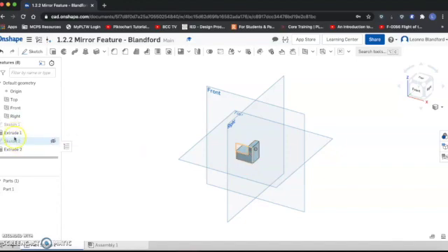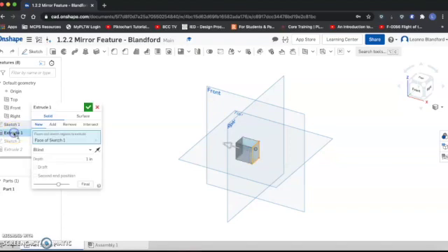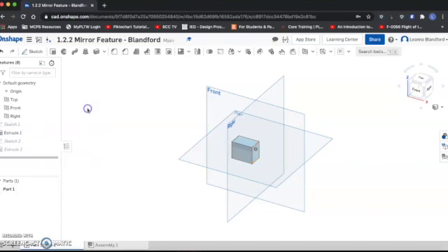When you notice on a drawing that you have an incorrect extrusion, you can go back to that feature. And I actually did my math wrong because it's 0.75 plus 0.5, not 0.25. So this is actually an extrusion of 1.25. And when I hit enter, it's going to automatically update that. And when I hit the check, it readjusts that cutout based upon that new number that I put in there. So that's a really easy way to fix mistakes.